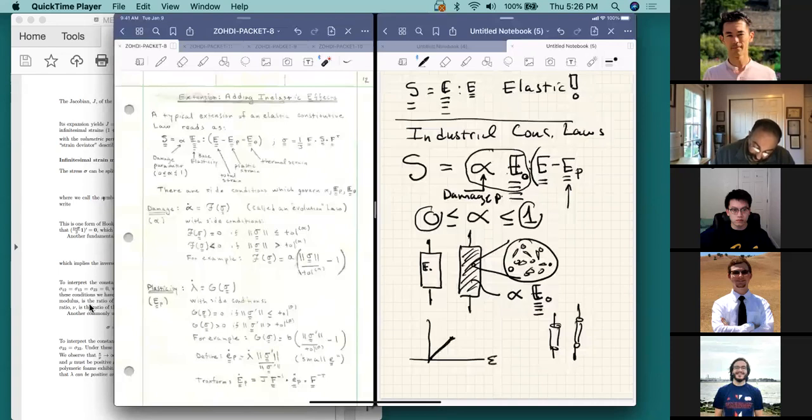We usually take the strain versus stress. And when the material starts to plastify and we let it go, it comes back down to some point here. And this amount here is usually referred to as the plastic strain. The models for this are somewhat complicated because this is not an easy thing to put into a constitutive law, because as we pull on the piece of material and then let it go, if we pull on it again, it starts from here and then we let it go and it comes back here.